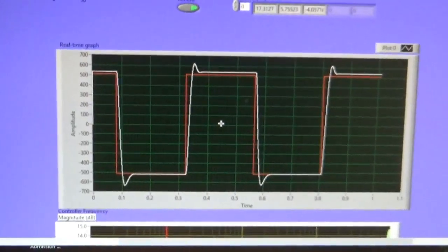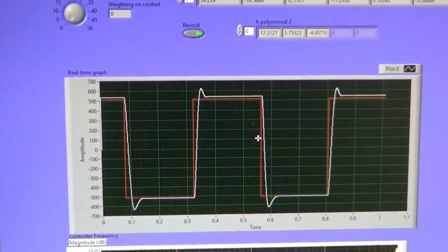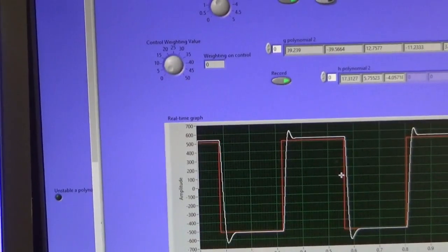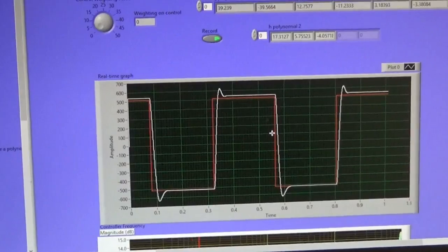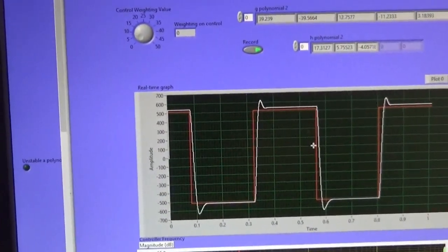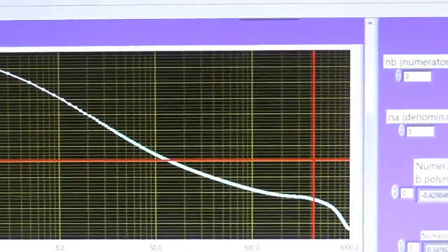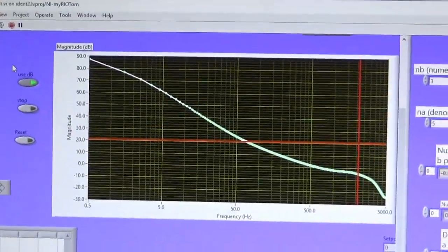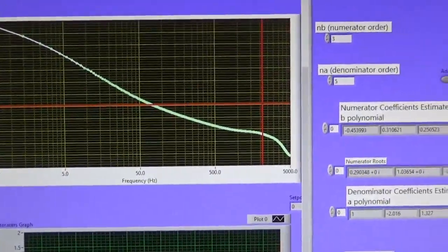There's a little bit more overshoot this time with the lower weighting. Okay, and now that can be improved on. Of course, we can put another integrator in if we need to. We can perhaps look at that. Change the weighting, but we don't have control over bandwidth. It's just how it is naturally. I'm going to run it one more time and just put a manual set point in. Again, we needn't necessarily identify it every time. I could skip straight to the actual thing itself.